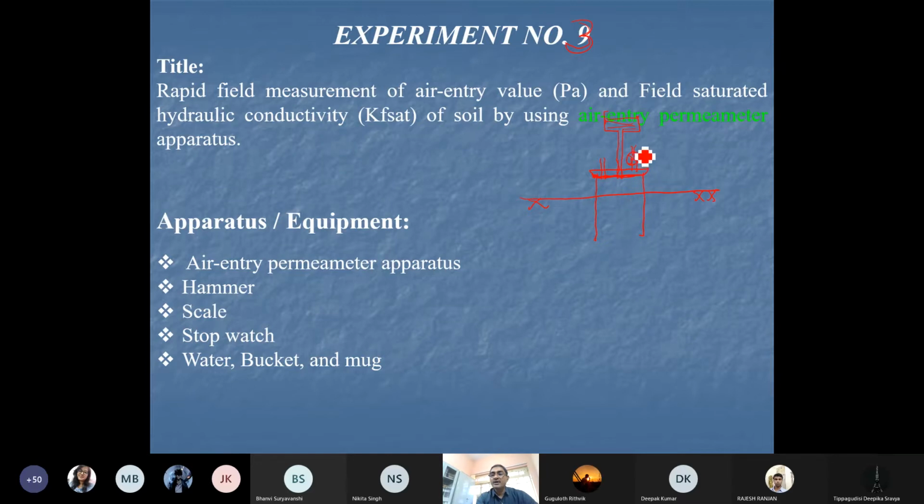So we have the air removal valve, the supply valve to this system through the reservoir, and we have one opening here which is connected to a pressure gauge. It is called a vacuum gauge, to measure the vacuum which is generated inside this system at any condition. Let me first tell about the instrument and then I will say when this vacuum is generated.